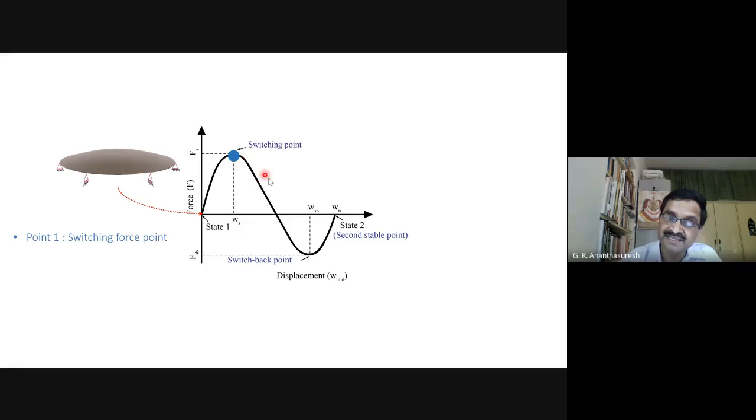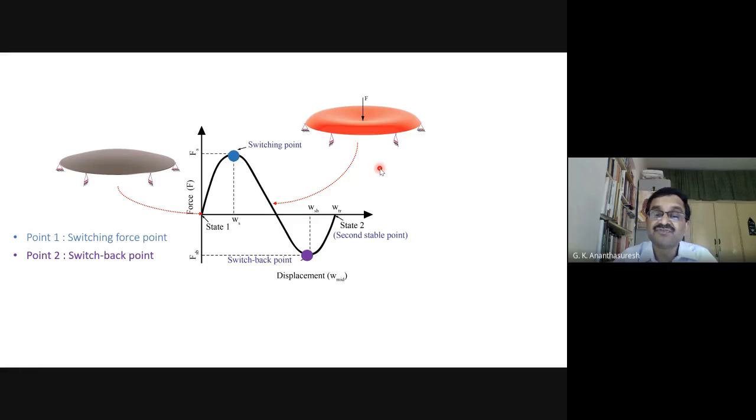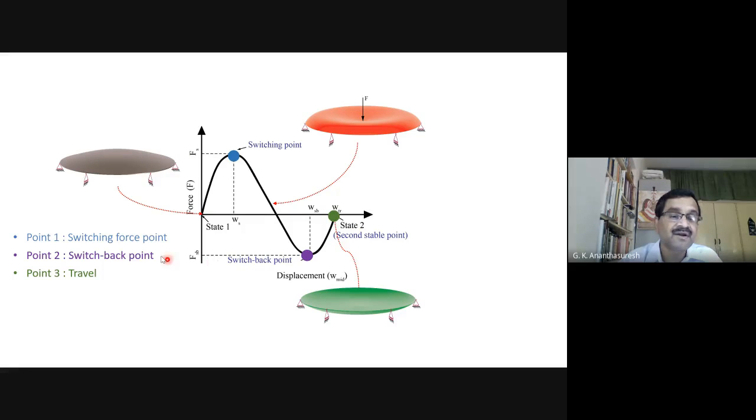That is, it enters the negative stiffness region here. And this is the negative stiffness. You are doing that, and it just wants to go. Everybody has this experience of the shells. If you press, it'll resist, but after a while it will go by itself to the other state. And that's what happens at this other switchback point when you're coming back. What was concave up here becomes convex up, becomes concave down. That is the bistability.